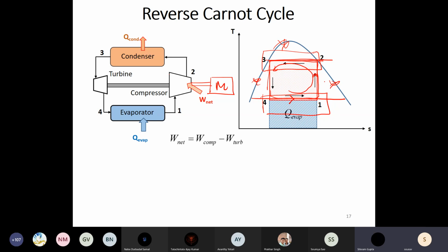If you look at the isentropic efficiency of a compressor in your refrigerator, it is around 65%. An AC will have somewhere around 65 to 70%. The large compressors that we use in our Nalanda refrigeration system are again close to 75%. That is the maximum that we have been able to attain. But still, we can envisage that we can probably push it to 80%. So we can attain the isentropic process with 20% inefficiencies.